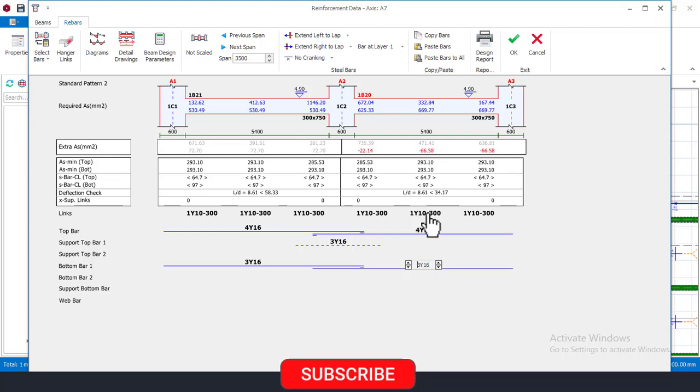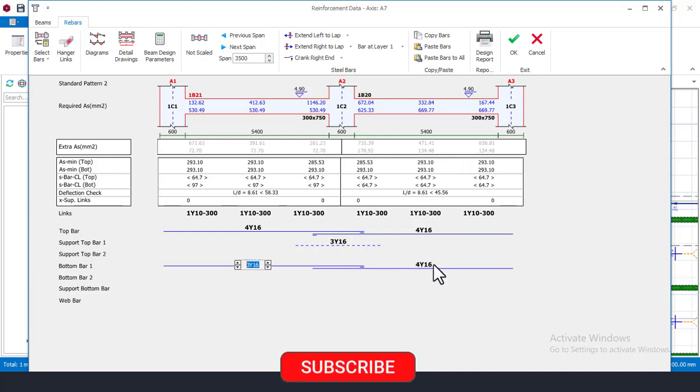Okay, so right now I'll come here first and then reduce this to 16 first, and then it is fading here. I'll come here and then increase to what? 4 numbers, which is okay. And I'll come again just to have a good uniformity all the way down, because they have the same length. I can see that these two spans have the same length, which is 5.4 meters, and the same thing here. So just to avoid confusion during the construction of this building, I'll also introduce that to make it 4, so that they will have a smooth laying of their reinforcement, 4Y16 at the bottom at the row.